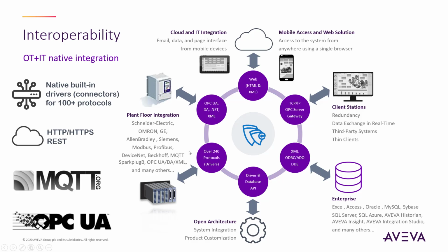Well, that's of course the basics of this, but we can communicate to multiple PLCs, multiple drivers simultaneously, allowing you to be a gateway between different brands of PLCs, as well as connect up to get information from any of these PLCs and send to any of these other destinations, whether it's a 20-year-old serial-based temperature controller, collect that data, send it to a database, get that information in and send it to OPC, pull information from the web, send it to PLC.